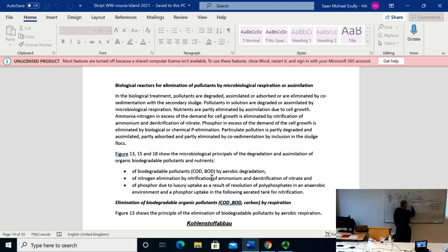What then happens is those two sludges go into the digester, and 50% is degraded, also of the proteins, and this is also protein, the 1 gram. So you have 3 grams, and half of it you get back, 1.5 grams.